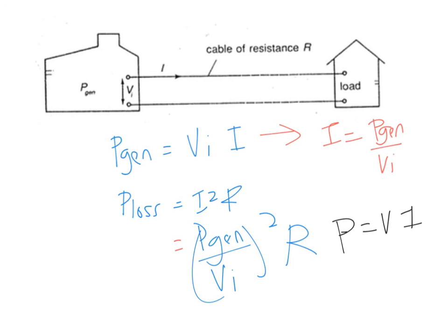If you remember Kirchhoff's law in your AS, the voltage of your supply, which is your EMF, equals the sum of PD in the circuit. So it will be this PD plus this PD plus this PD. So the voltage here is talking about the PD across your wire, which won't be the same as this. Okay, so don't confuse.